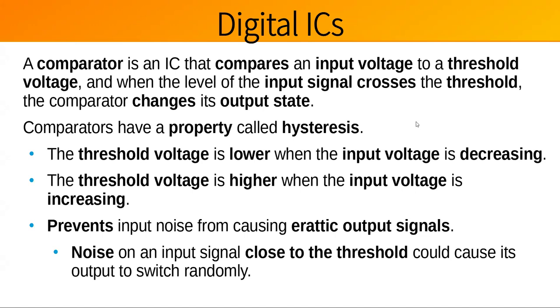One of the things that they put in a comparator is a hysteresis circuit, so that if you exceed the threshold voltage and turn it on, and there's a little bit of noise, and it drops below that threshold voltage, instead of it turning off, the hysteresis circuit requires that it drops a certain amount below the threshold voltage before it'll switch back to off or 0.